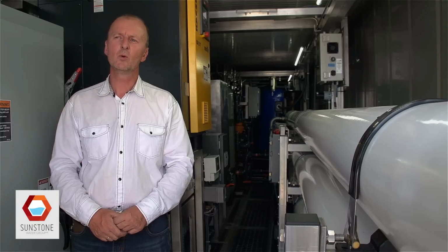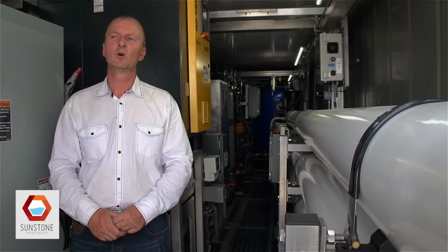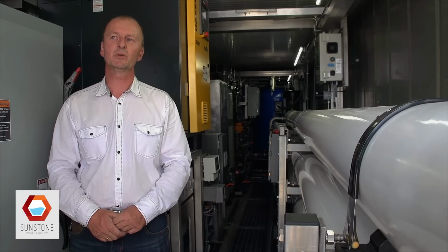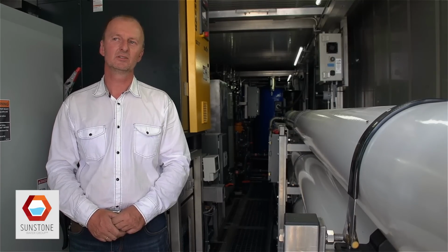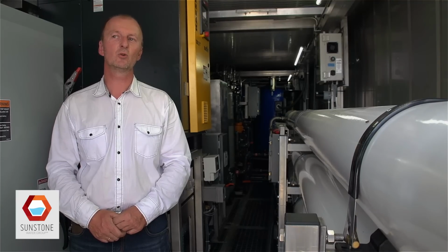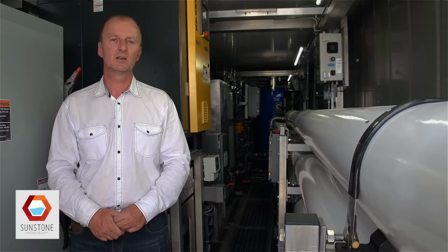To pre-treat the raw water so that it's available to process in our membrane, we need a quite advanced system. What you see here behind me is actually several modules and a lot of equipment. This is necessary to take all the things out you don't want to go into the RO membrane. If you don't do anything and you are sending your raw water from a well, like here in Texas, into the RO membrane, they foul quite easily.